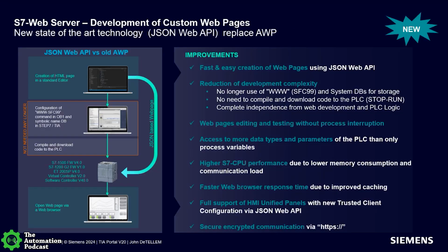Hopefully it is. Another significant thing, which is part of the controllers and actually a part of almost any Siemens hardware device, from the network switches, power supplies, drives, to HMIs, is the ability to turn on a web server of the device. Traditionally, turning on the web server provides you access to that device and a full footprint of the diagnostics and status of that device, whether it's a PLC or a switch or a power supply.